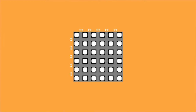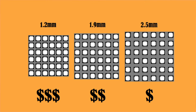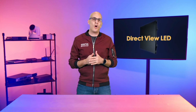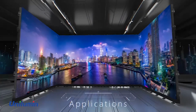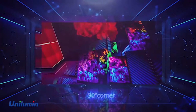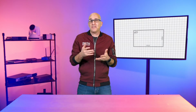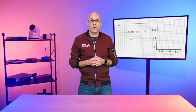Each panel is defined by its pixel pitch, which is the space between each diode on the panel, which is measured in millimeters. Typically, manufacturers will market them in configurations based on this exact measurement. So each panel of your dvLED wall is not a separate TV, but just a section of the overall image. Each panel only displays a few hundred pixels of your overall image, and the image quality improves the lower your pixel pitch. An HD video signal is made of more than 2 million pixels in total, so you need that many LEDs just to create an HD video wall.